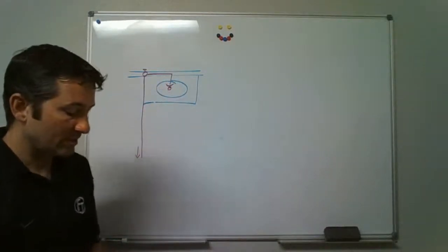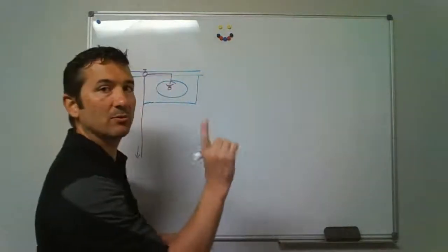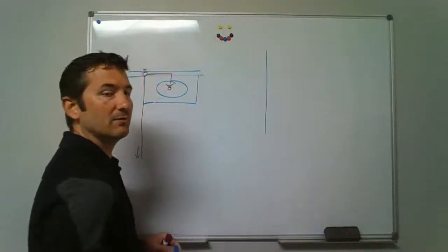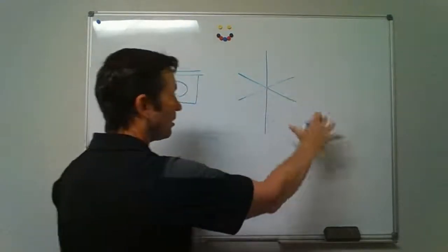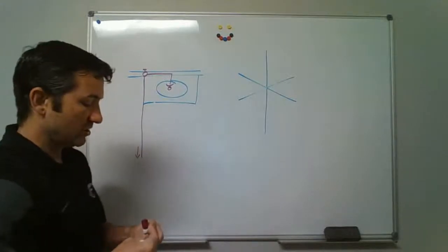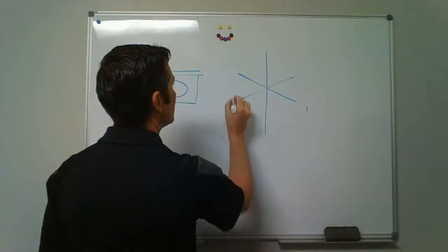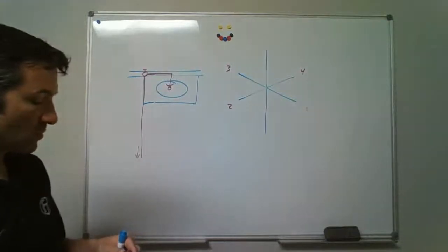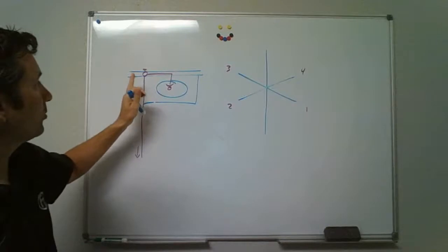As we look at this, you can start to convert it to an isometric drawing. You orient your paper the correct way so you've got vertical lines on your paper. That's going to be very important to you. And then you have the cross section. If you look, there's all this grid pattern over there at 30-degree angles for the isometric. And we said there's 4 possible angles that you could do this, and we just wrote 1, 2, 3, and 4. So when you start to do this conversion, you look and draw one thing at a time.